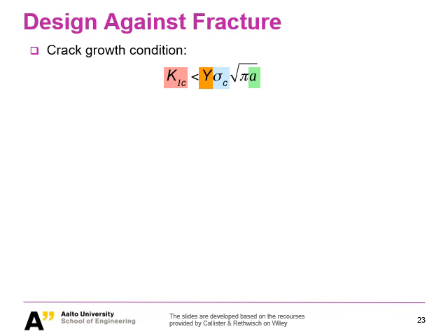Now you have got the point of fracture toughness, and you know it is a completely material intrinsic value. So finally, here we can establish our crack growth or crack propagation condition, which is when the right-hand side, these are reflecting, let's say, the extrinsic part of our loading or our geometry feature of the crack, bigger than the material intrinsic value, which is this K1C or whatever fracture toughness you're talking about.